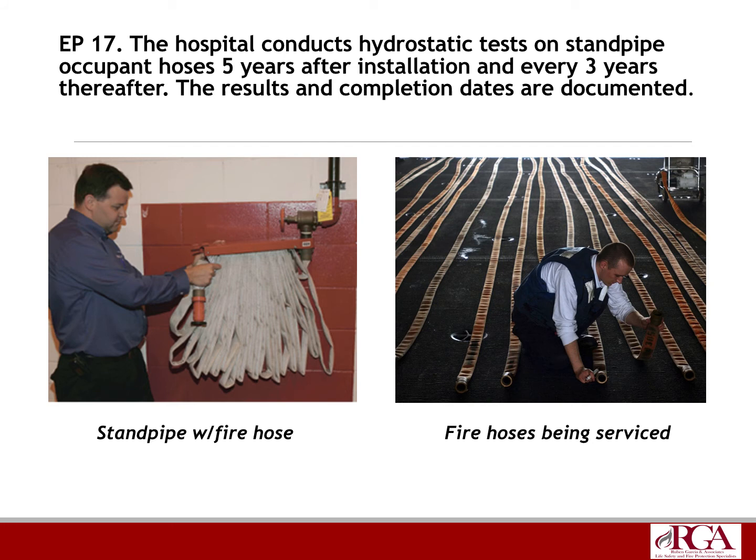EP17: the hospital conducts hydrostatic tests on standpipe occupant hoses 5 years after installation and every 3 years thereafter. So if you have standpipes and in the standpipes you have fire hoses, you have to have those inspected 5 years after the initial installation and then every 3 years thereafter. Basically, they have to roll them out, make sure they're not kinked up, and hydrostatically test them, pressurize them, make sure that they're going to be good to go.